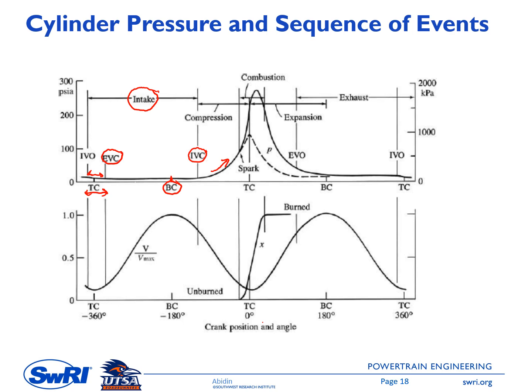So at some point before the piston hits top dead center, the spark will ignite the fresh mixture of fuel and air. There will be a combustion, and then there will be an increase of the cylinder pressure. So here, this increase is because of the combustion process. And then once the piston hits TDC, it will move down again, going toward BDC and doing an expansion process. In this case, we have an expansion process from TDC up to here, up to BDC.